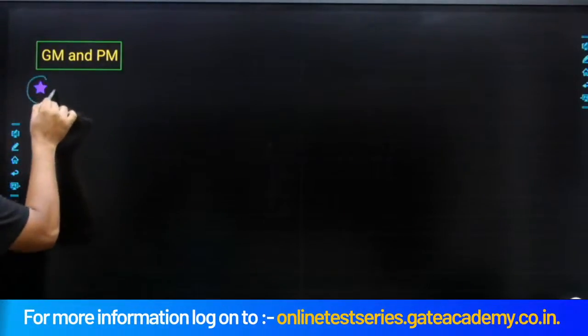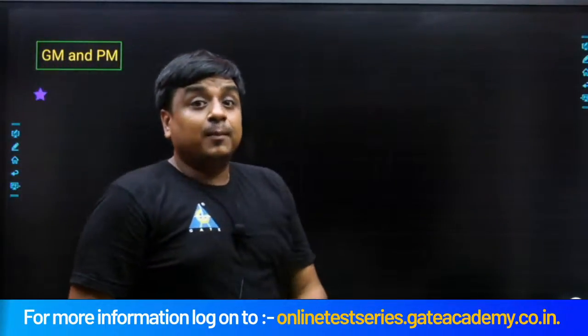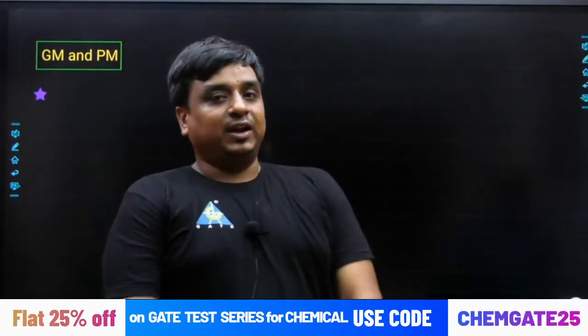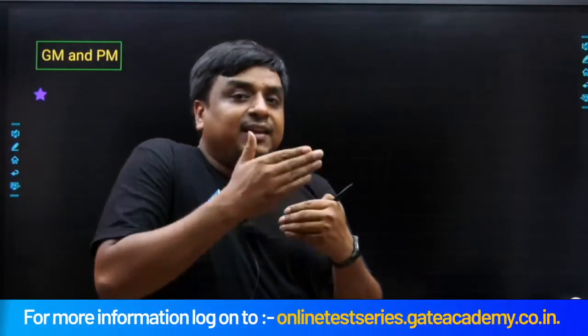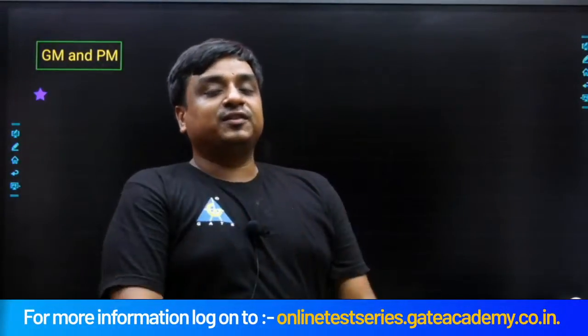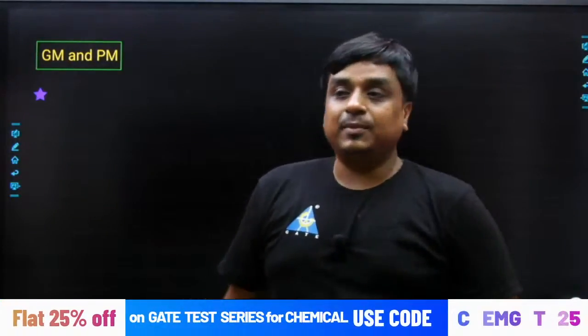What does it mean by the gain margin? My dear friend, the name itself is self-explanatory. How much margin we have over the gain before the system reaches the verge of its stability or instability. We assume the system is a stable system, and let's take the gain K being increased, and after a certain amount the system becomes unstable. So the gain K we can provide up to the verge of stability is said to be the gain margin.